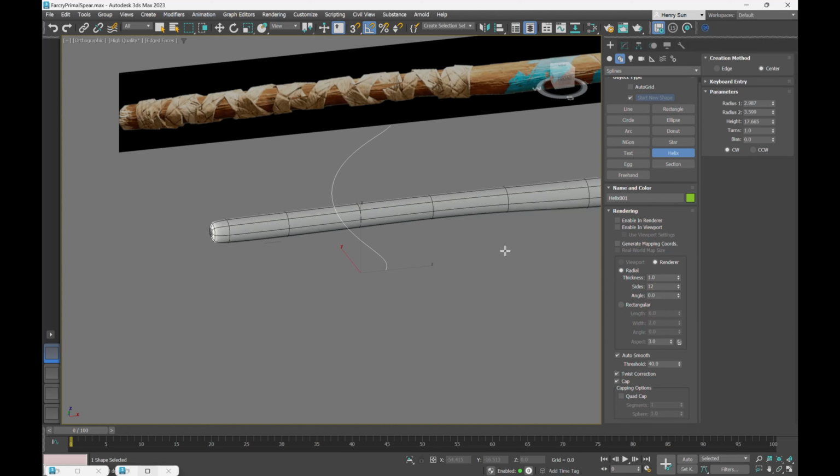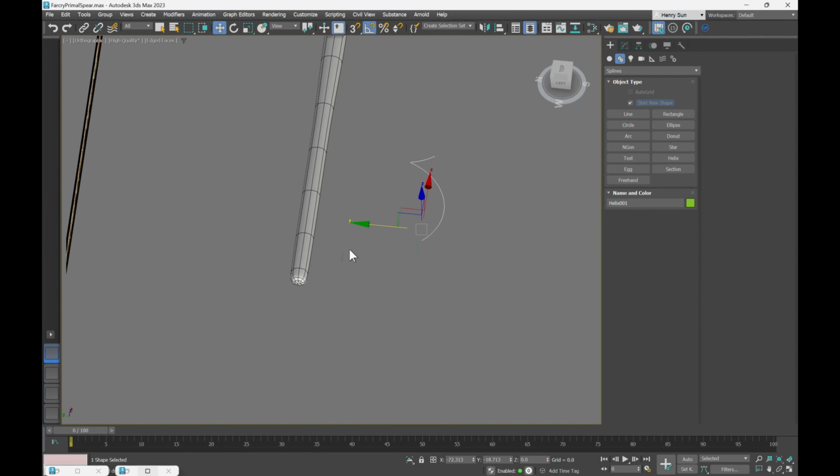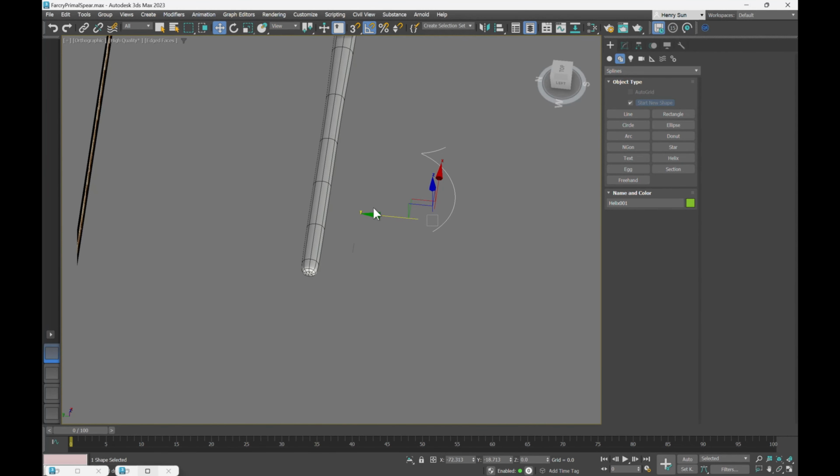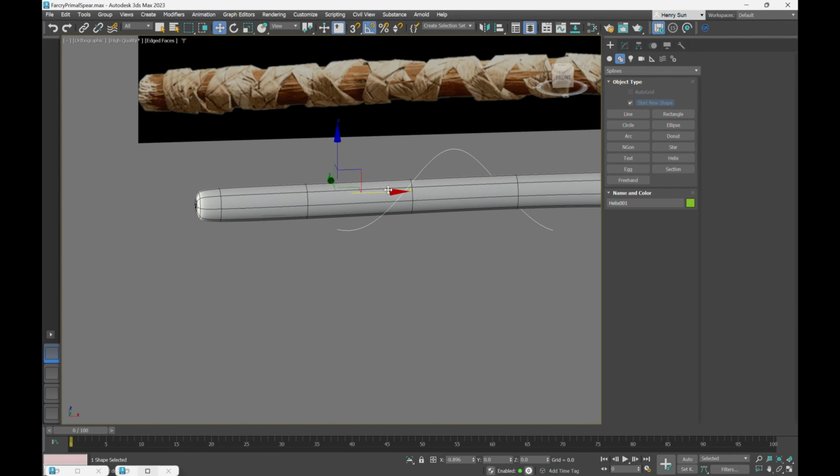So let's just right click to cancel that tool, and let's scale that and move that into place. So making sure we have our rotate snaps turned on, which is up here, or A on the keyboard. Let's just rotate that 90 degrees, and let's move that back in the Y direction. So I'm just going to go down to our transform boxes down at the bottom here and just right click these little spinners. Great. So let's move this back,